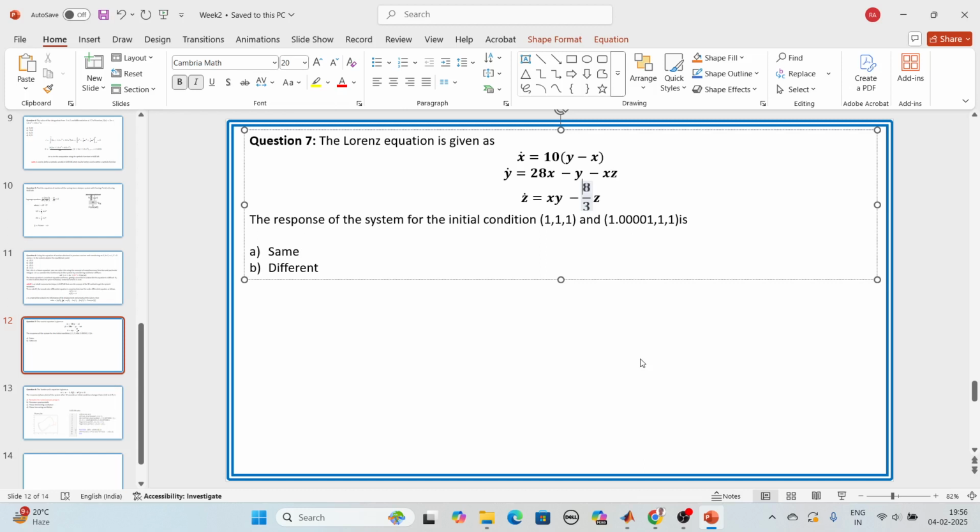As I told you about a bifurcation in the previous live session, with the change of some parameter value, we have the change in the equilibrium points, right? Similarly, for the dynamic case, with the change of the parameter value, we have a difference in the dynamic behavior. If we get that bifurcation diagram, we know that for these parameter values I'll have a periodic solution, for these parameter values a quasi-periodic solution, and for these parameter values a chaotic solution. So we avoid the parameter values for which chaos is there, right?